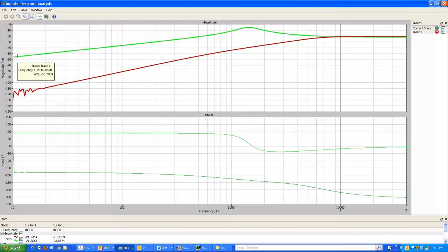So you can see that under low frequencies it will become even larger when you go to even lower frequencies. Even for 10 Hertz there is at least a 60 dB or a factor of 1000 reduction in the output impedance. So the closed loop gives you a much better response to step load changes, meaning the output voltage would deviate by a significantly smaller amount.